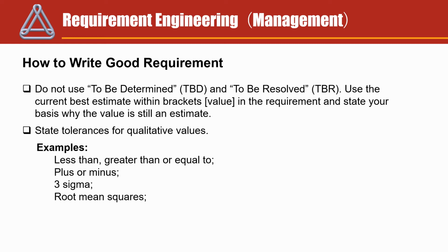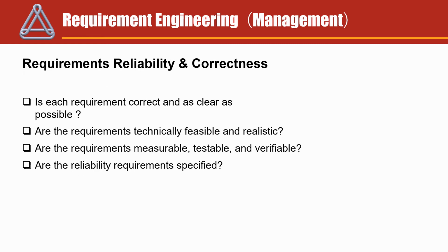So the plus or minus 2 accounts for that spread. Another thing could be the 3 sigma accounts for maybe variability in conditions in manufacturing. But it's better to get a ballpark number there than to say something like the boat needs to go fast, because that's ambiguous and subject to interpretation.